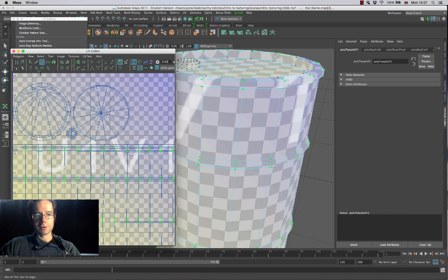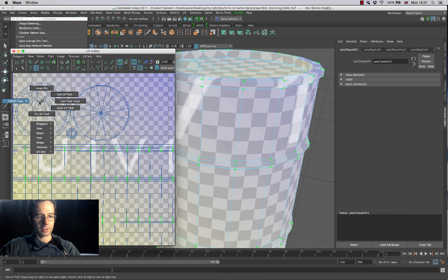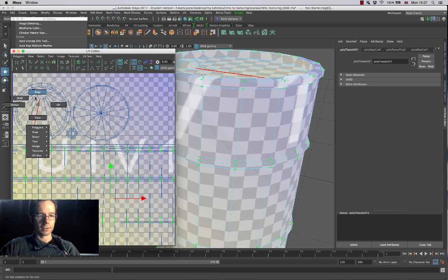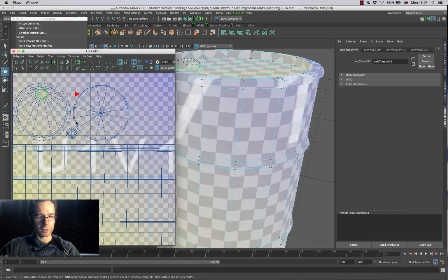Again, be careful because there is a sew tool over here, so if I wanted to, I could make selections of my UVs and just drag along, and they would automatically sew themselves together again. So if I wanted to connect this up over here, I technically should be able to come in here, grab myself my UVs, do a little selection of the UVs in here, and I'll do a selection of the UVs here and here. And if I wanted to connect these together very quickly, I could just come into here and basically start painting away on these if they are in the same space.